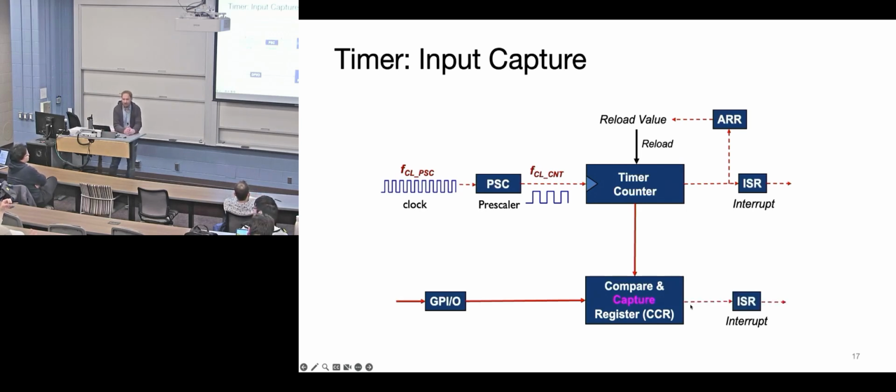Okay. When do you use clock div versus prescaler? When do I use what? Clock dividers versus prescalers. Prescalers are much more flexible. They actually give you a division ratio, which is nice. Clock dividers are simpler. They're really just some flip-flops. So in your clock distribution tree, you usually have clock dividers because they're simple, like this divide by 2. Prescalers are more flexible but larger. Does that make sense? Yeah. I think there's a slide on that that shows you the difference between the two.